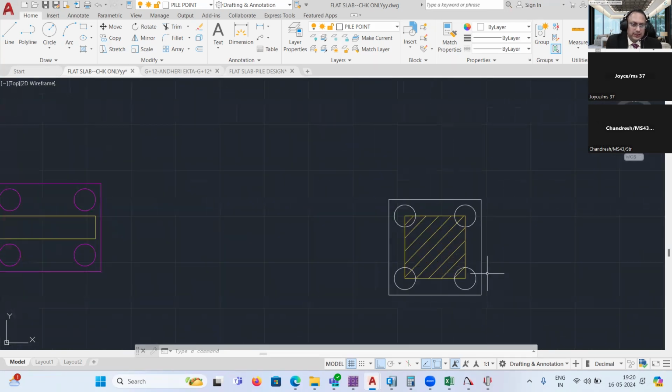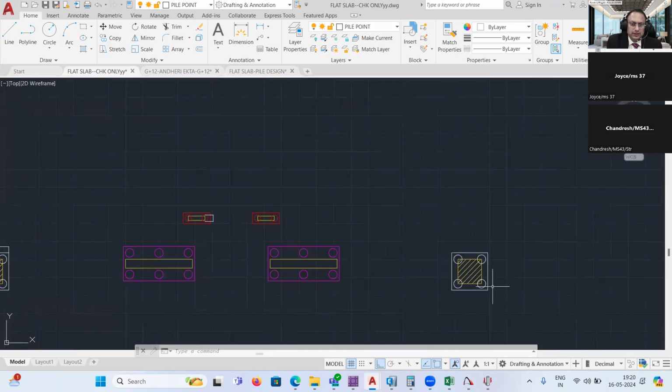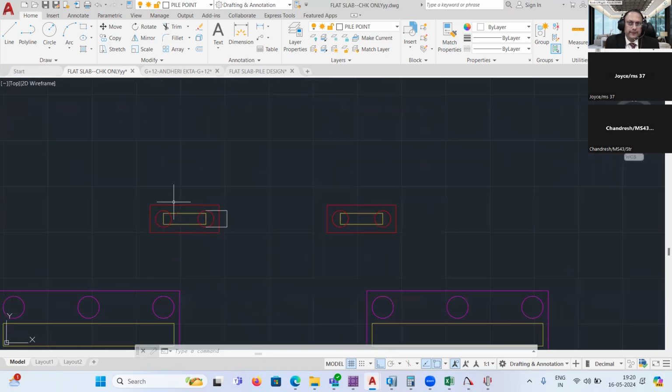Yeah, like this, correct. So even if this was a single pile, would it have been okay? Or because it is a shear wall, is there something like minimum of 2 piles is required? Minimum of 2 piles. Why is it required? Tell me. Because it might have overloading. See, there is a force and there is a bending.